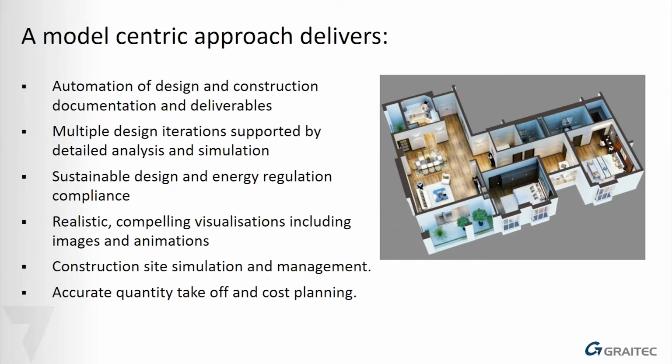The other thing we've got is the ability to have what we call multiple design iterations. So this is like design options. I'm going to show you an example later on where a house design is being drawn where the exterior has got the option of either being a brick finish or a rendered finish, and all the information that links to the differences about the construction. It's not just about changing the material, it's about changing the wall construction. So we haven't just got a case of block cavity brick with a render added afterwards. It would be a different type of brick that we would then be rendering over.